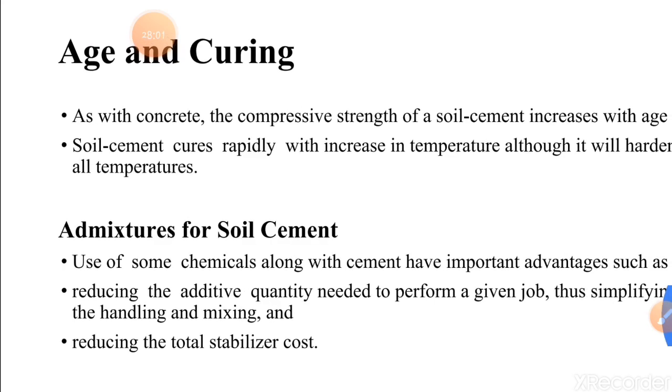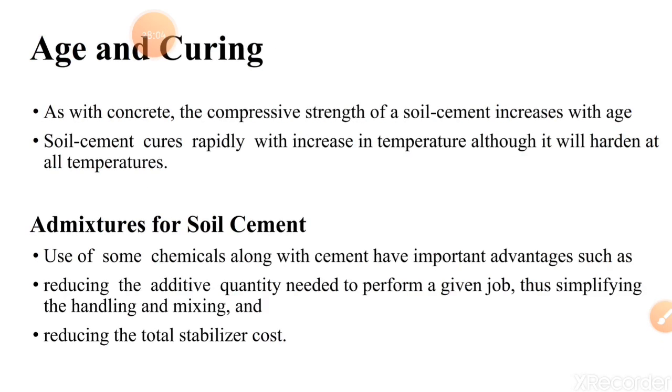Curing will be the last step in soil cement stabilization. As with concrete, the compressive strength of soil cement increases with age. That's why curing is essential, so that the hydration process gets completed fully. Soil cement cures rapidly with increase in temperature, although it will harden at all temperatures. If the temperature is high, it cures quickly, and it will get the required strength quickly.